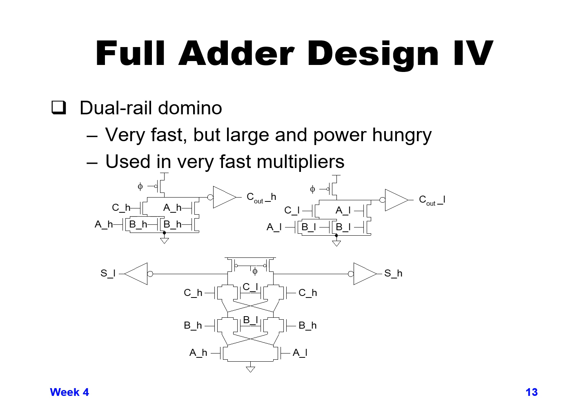It can be larger as well, but the power is what usually is more limiting in today's technology generations. But it can be used for some applications, in particular multipliers, where you need to do a lot of multiplication very fast. And there are some usages where power is not a concern for some people, and so they'll design in a dual rail domino technology such as this.